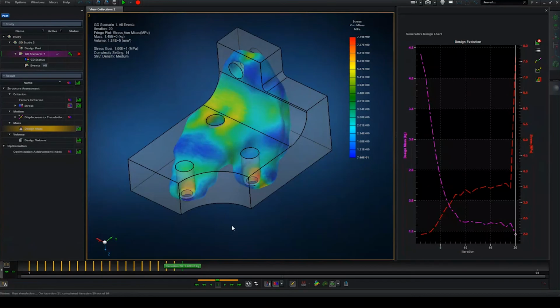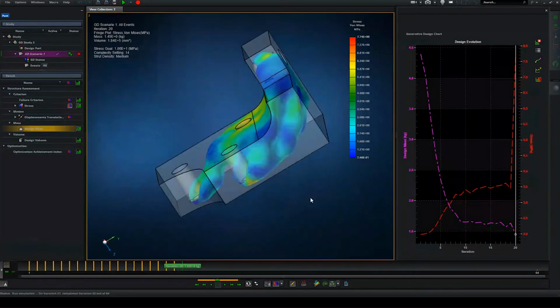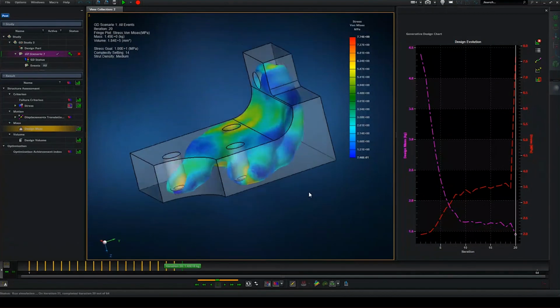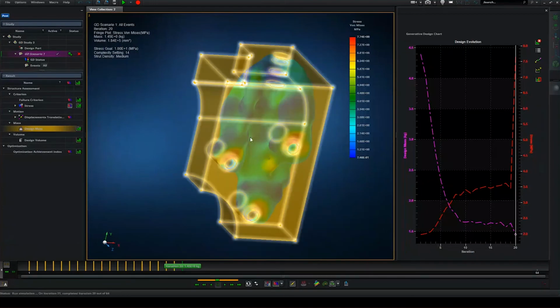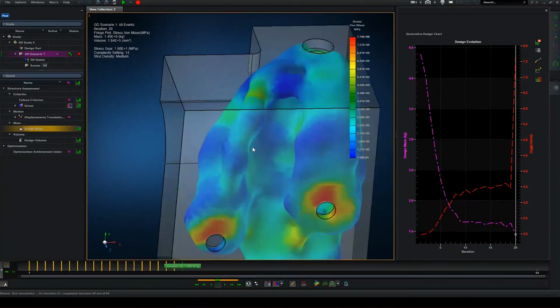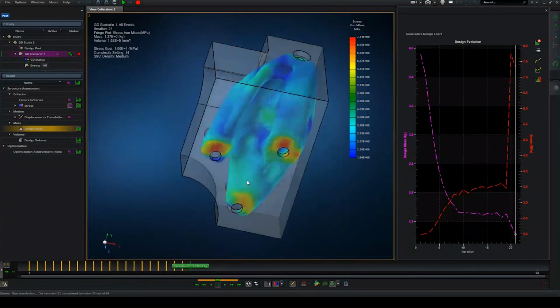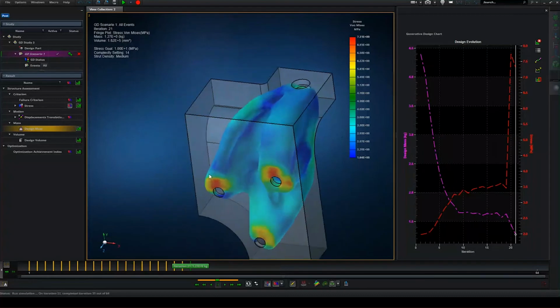Important to note that at certain iterations, the resolution increases. So you might see weird interim results that look like they've got some thickness, like these little bumps. But in the follow-up iterations, those typically disappear again. So don't worry if you see strange results. There you can see now those lumps disappeared in the follow-up run.